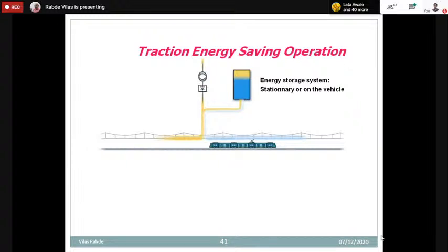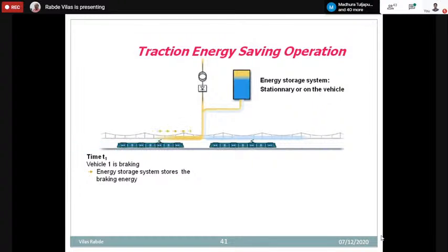Now the train is coming into the railway station, and it is halting. Brakes are applied. These are dynamic brakes, not conventional brakes which convert energy into heat, but they convert energy into electricity, and that is stored. See, now this has come. Energy is stored in the capacitor. We will watch it again. The train is coming to the station. Brake energy is getting stored into the capacitor.